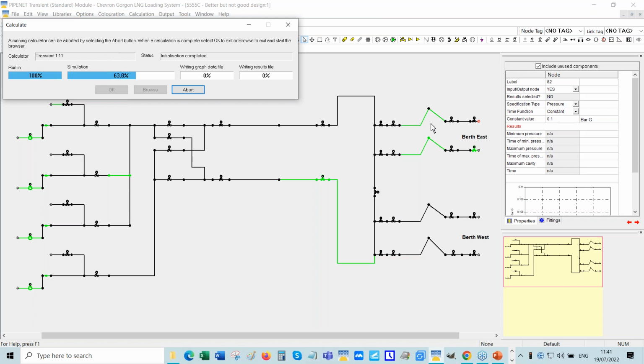You see, the point about these cavities forming here is, even if the cavity collapsing doesn't give a very, very high pressure, it's still problematic because you can get these oscillations in the cavity volume curve, which is something you want to avoid. And also the cavity collapse could produce vibrations due to hydraulic transient forces in the system.